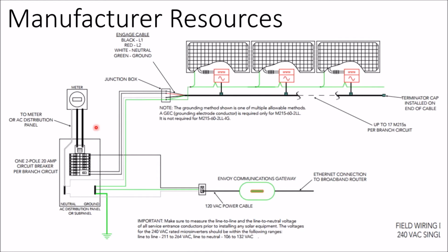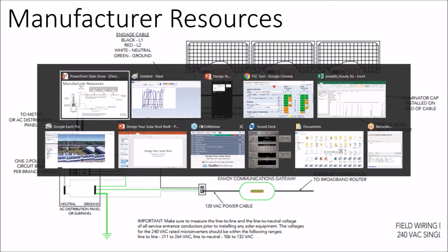And so here, the electrician may not know what they're doing, but if you talk in their terms, like saying, well, what I need you to do is run me a 240 volt branch circuit up to the rooftop and terminate in that roof mounted combiner box, they can get right to work. So it's all about, they've never done solar before, but all this stuff is pretty plug and play. Now let's take a break for a minute and watch a video.